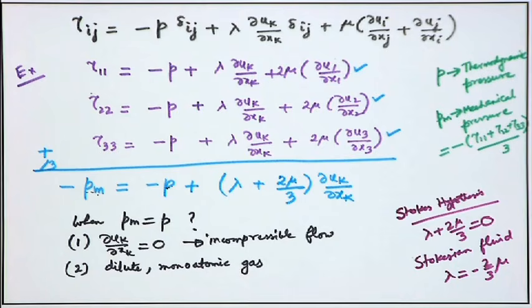Then the time scale of imposition of the change is very fast, and if its relaxation time is not that fast, then the fluid cannot relax to a new thermodynamic state before a new change has taken place, and then it cannot equilibrate its properties so that it can convert all the degrees of freedom to the translational degrees of freedom instantaneously.